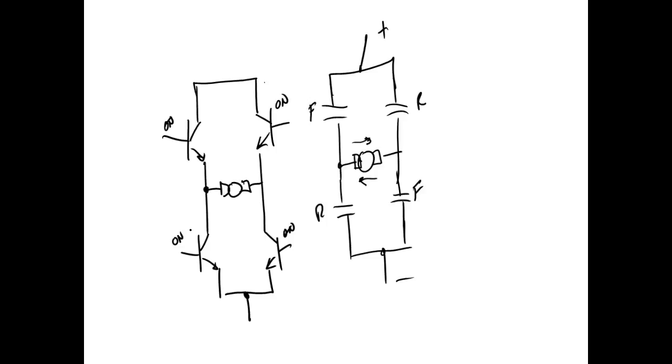So you can buy a solid state H controller, which is basically transparent to you. You have a switch on the outside that says forward and reverse. You hook up two wires that say forward and reverse, and the electronics inside the thing does everything else. Now, what's the advantage of using electronics? A lot quicker. And plus, you're only dealing with electronics. Plus with this, we can use pulse width modulation to control the speed of the motor. This right here, not only could we change the direction, we could also change the speed using what we call pulse width modulation.